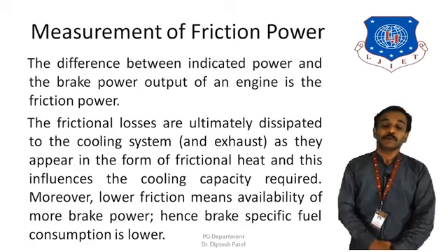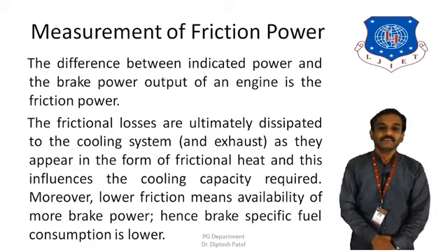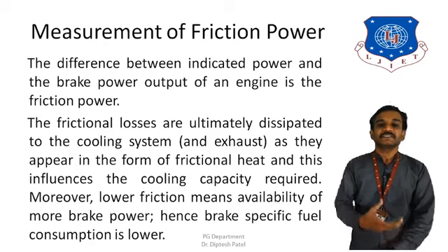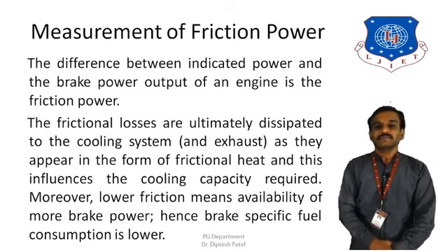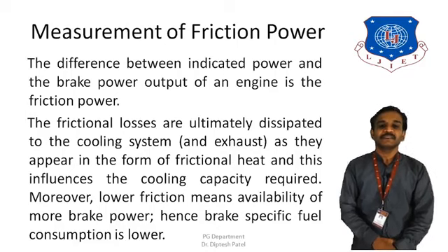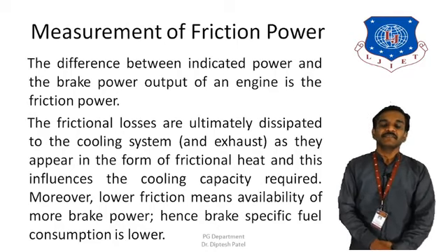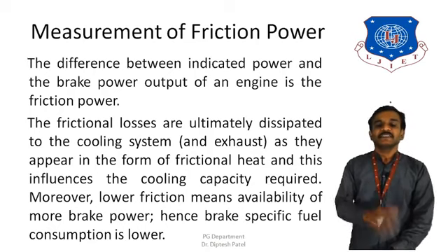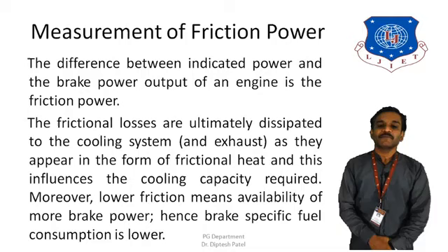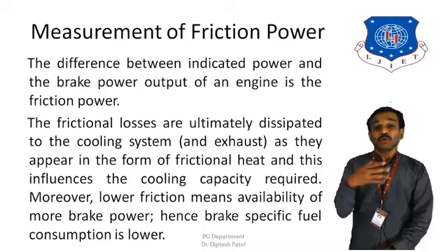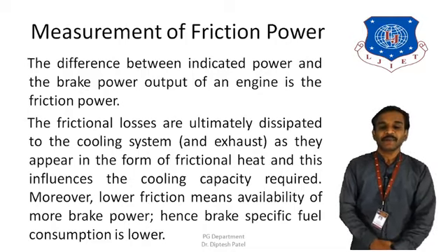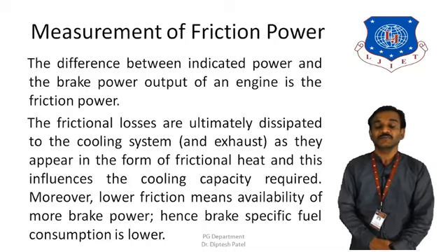It takes away a certain amount of the power, and these losses are normally converted into heat, which is dissipated with the help of the cooling system and the exhaust. So all these friction losses appear in the form of heat, and they also affect the cooling system. If the friction is higher, then much more heat will be generated, and therefore we require an effective cooling system as well.